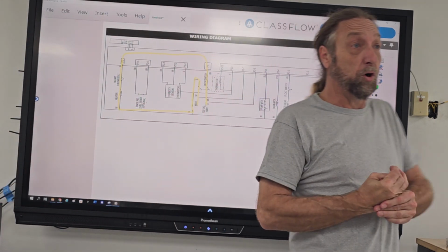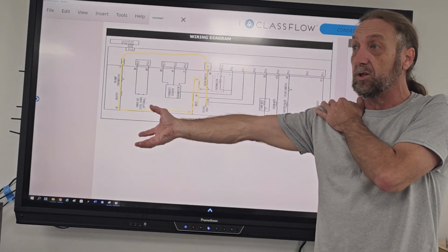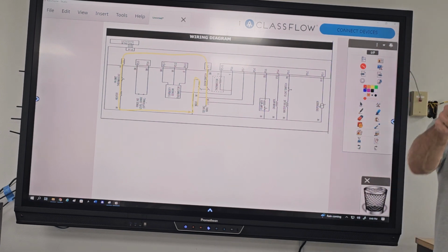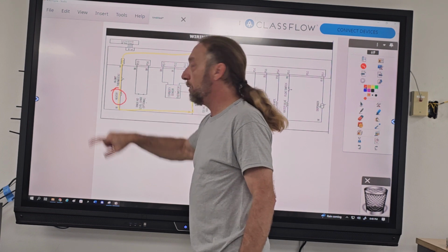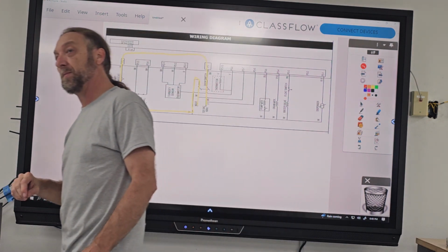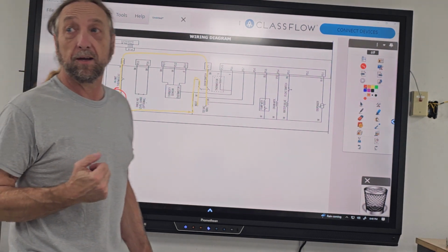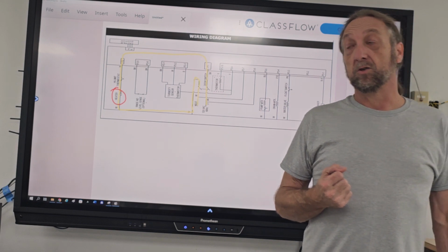So we're looking at the heater circuit, because the heater circuit is what dries the dishes, right? Okay, so anybody else? Hold on, Jim, let's see anybody else? Yes, Ricardo? The heater. I'd check the heater. What kind of test would you do on the heater? You could do an ohms test. Can you do any other tests? The voltage.